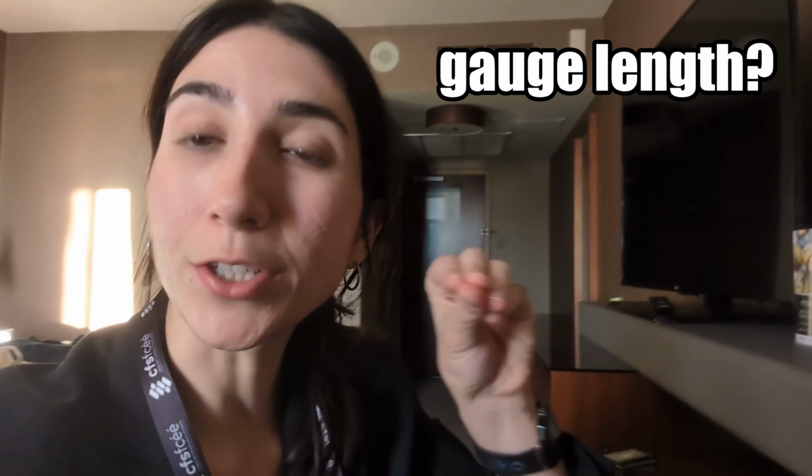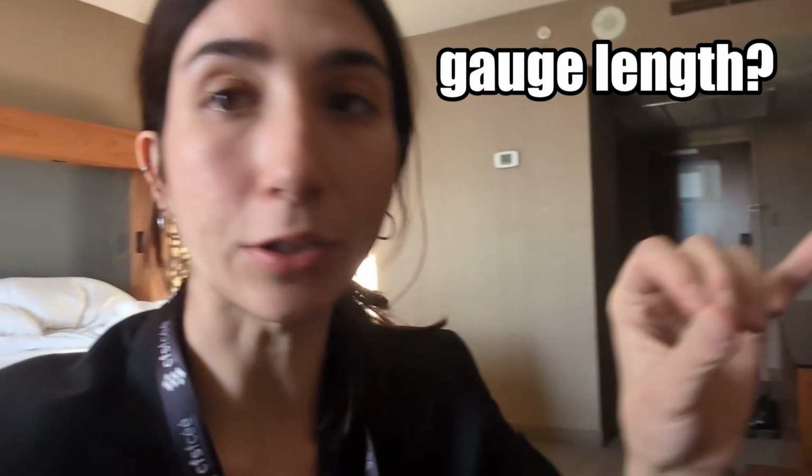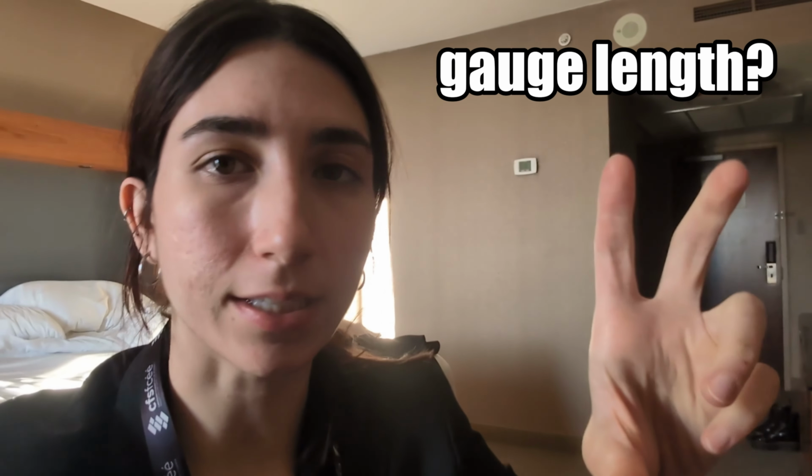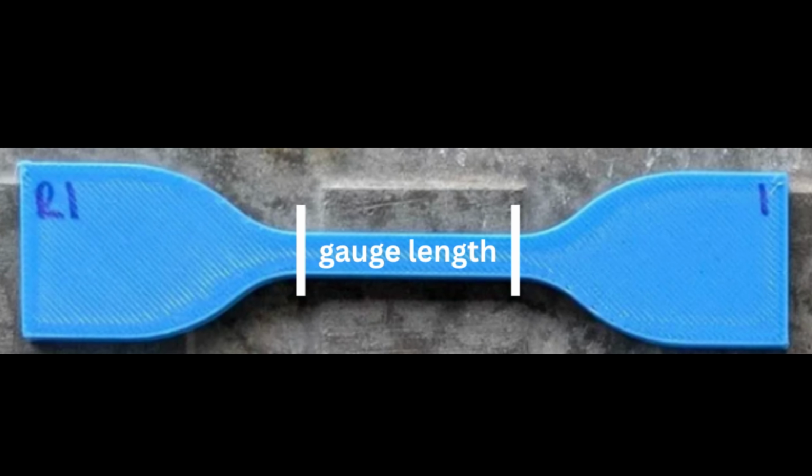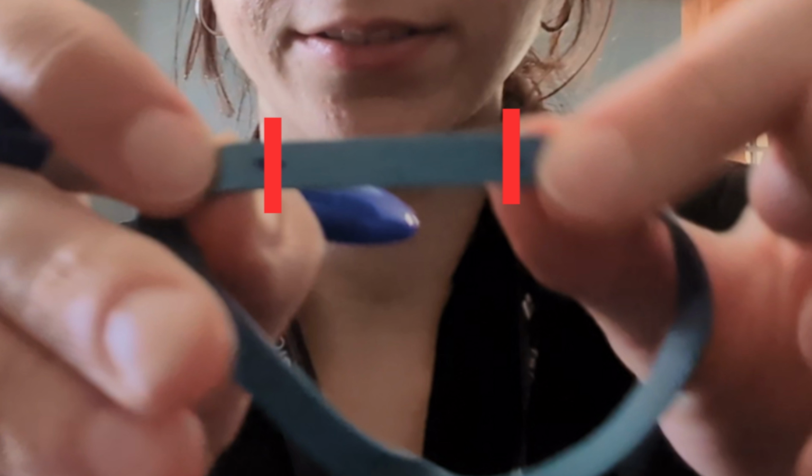I think it's worth me mentioning or defining exactly what gauge length means. Usually in tensile testing, based on the standards, it's like this dog bone dumbbell shape. The gauge length is that little straight piece in the center and is the only section of that sample where we care about measuring the strain. So for the rubber band that I showed earlier, it would be in between those two dots. We don't care about how that rubber band stretches outside of those two dots.